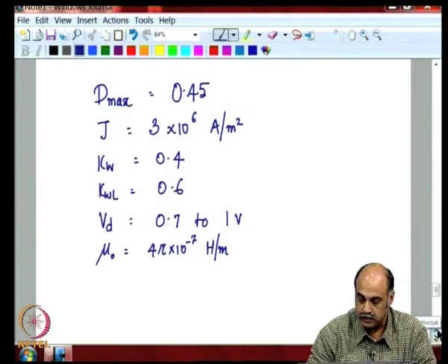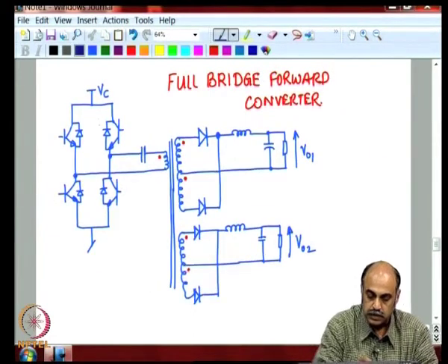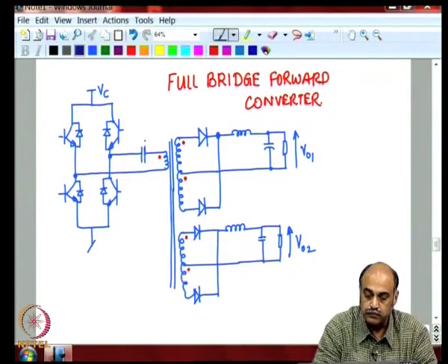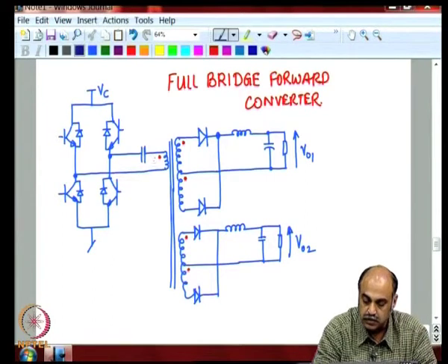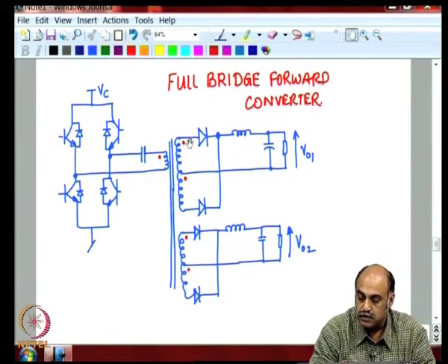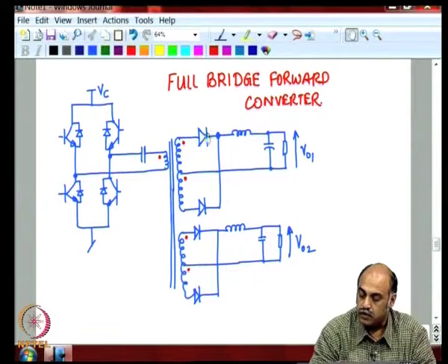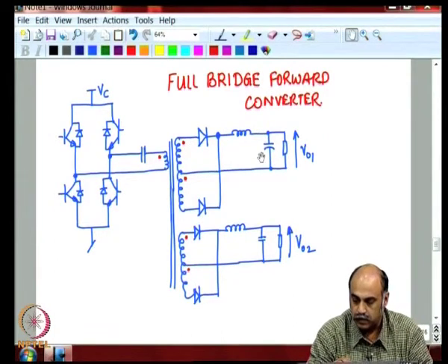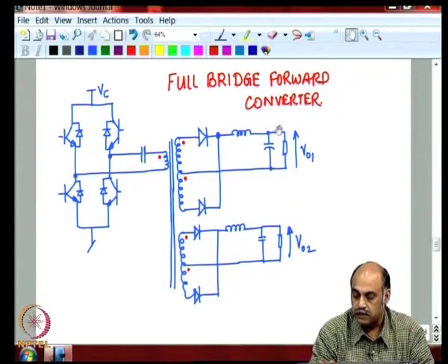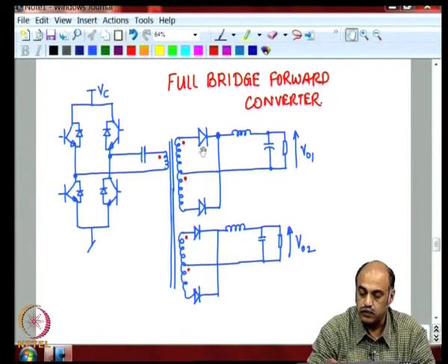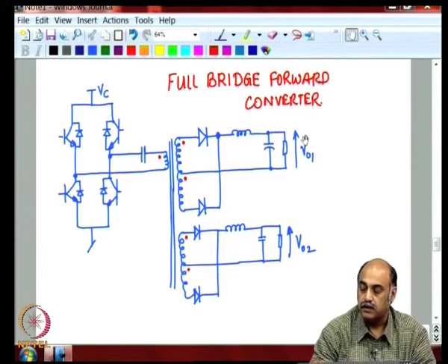Now, if you look back into the circuit, you will see this is Vc minimum, the worst case, minus around 10% of Vc max, which drops across this capacitance. So, that would be the voltage that occurs at the primary of this transformer. Now, N times will be transferred onto the secondary here, and with all the various drops just discussed. Okay. So, into D max times, because if this is minimum, the max duty cycle would be maximum, what the value that you would get here.